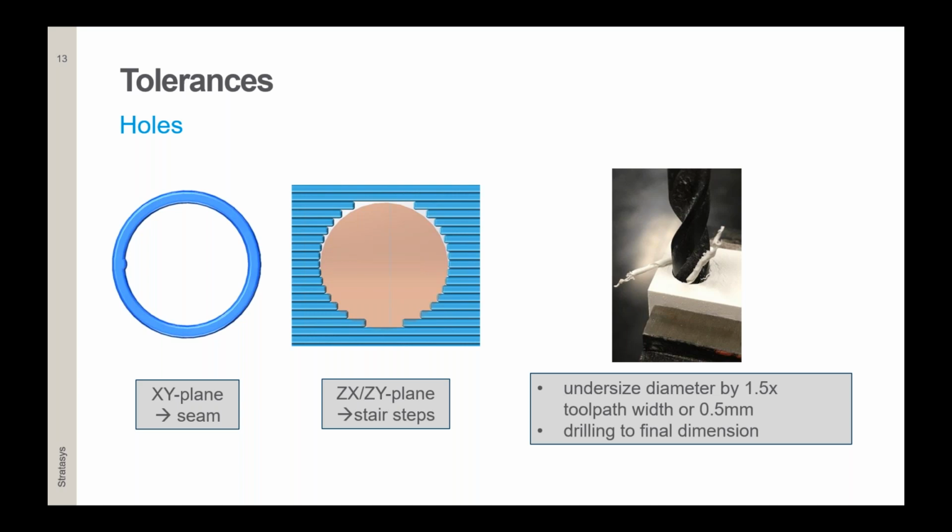Of course, you will still have the tiny bump, tiny seam, but you don't need to think about support inside the holes as when they are printed vertically, and the operator does not need to do additional steps in order to remove support if those holes have a diameter less than 6 millimeters, and it will be a little bit easier. So horizontal position, or printing it in the XY plane, is what I would recommend for those holes if possible.